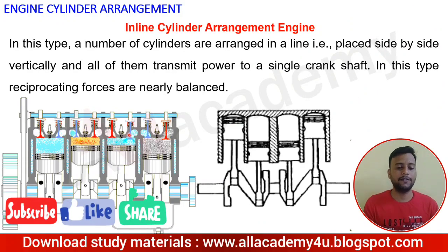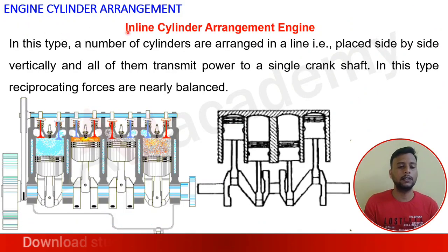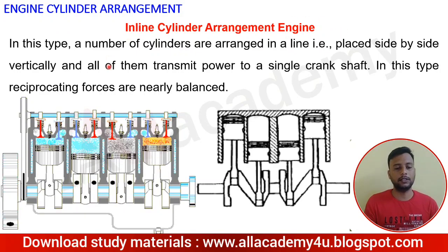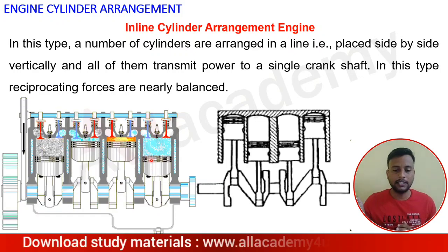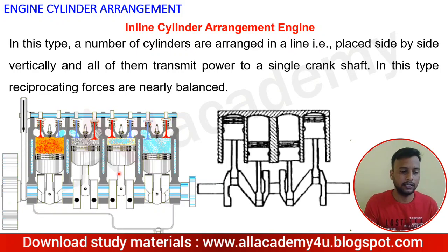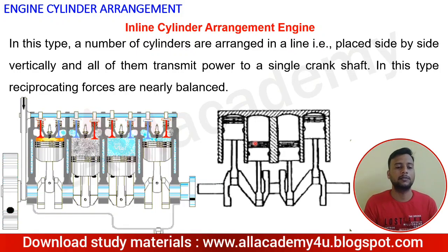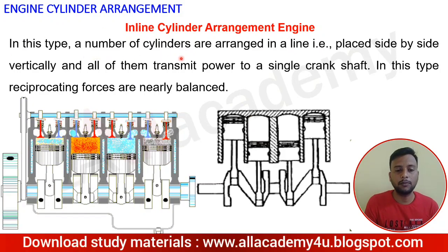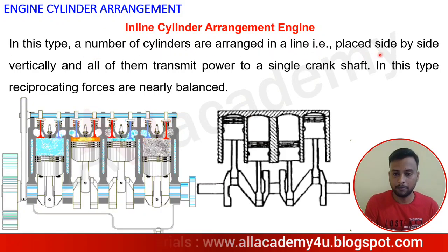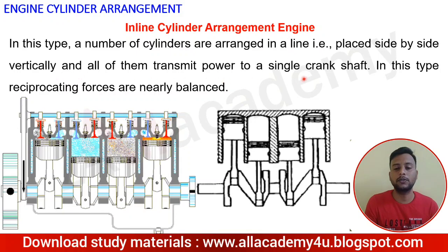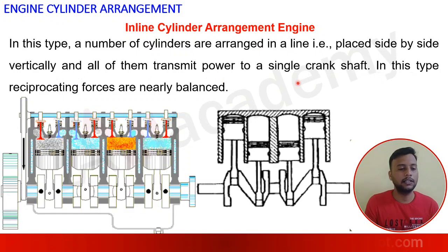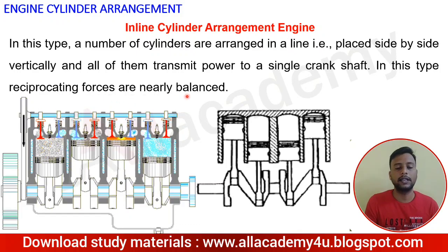Now here is the first one, that is the inline cylinder arrangement. As the name itself indicates, all the cylinders are arranged in a line. So here you can see this inline cylinder arrangement. In this type, a number of cylinders are arranged inline, placed side by side vertically, and all of them transmit the power to a single crankshaft. And in this type, the reciprocating force is nearly balanced.